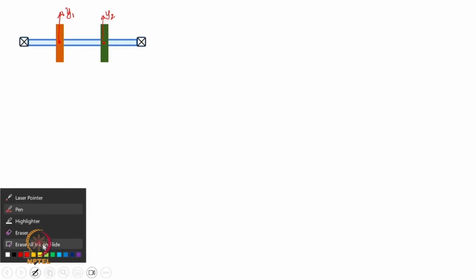We will discuss later on in this course how to get around that limitation, but the moment you start including mass which is distributed throughout the length, then lumping it also does not work out to be an accurate approach. So, we will find out through numerical methods how to take into account the shaft mass. However, let us look at how we attempt this problem. The shaft is massless, the discs have their own weights, and what we are going to do is,